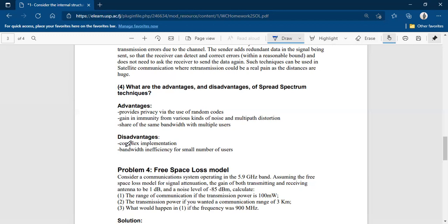And then if you are increasing the bandwidth and you are having a small set of users, right? You are redistributing the same message signal, like I showed you, over a wider set of frequencies, isn't it? Once you are spreading that over a different range of frequencies, the number of users needs to be large, right? When you are increasing the bandwidth, the more users there are, the more you utilize the large bandwidth that you have, and you can utilize it much better, right?